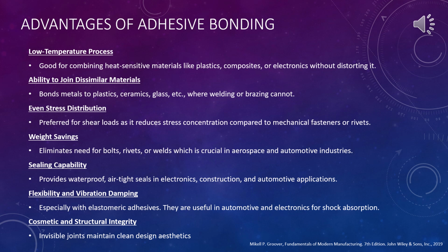Advantages of adhesive bonding. So the first one is the low temperature process, which is good for combining heat sensitive materials like plastics, composites, or electronics without distorting them. Unlike welding or brazing, adhesive bonding occurs at or near room temperature, which is really ideal for thermally sensitive components like plastics, thin metals, or electronic boards where the heat can end up warping, melting, or degrading the material.